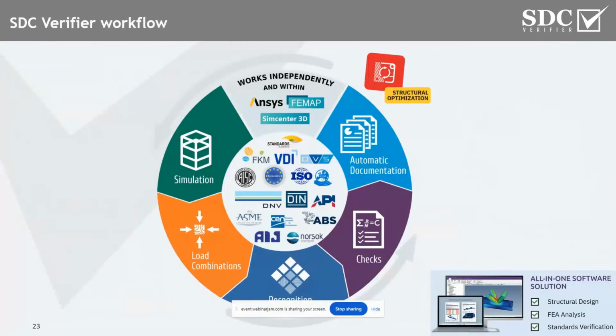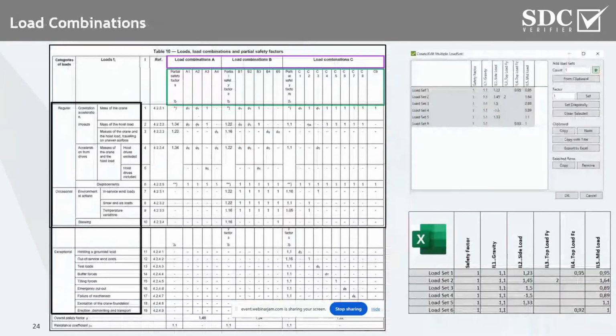And yeah, at this step, after the model is created, an essential step is, of course, to account for multiple load cases. So you might have seen, of course, different examples of standards, like this one you see on the screen, where you have to combine multiple loads with each other, apply partial safety factors, dynamic coefficients, all these kinds of things, consider different directions of wind, positions of loads. You end up with really, I don't know, hundreds or even thousands of different load cases.